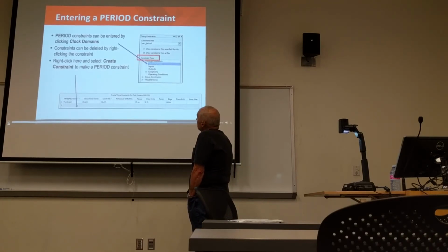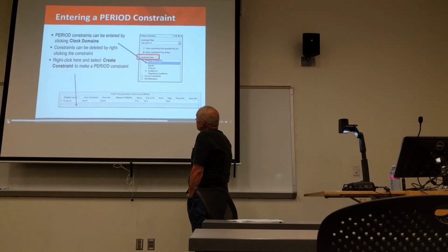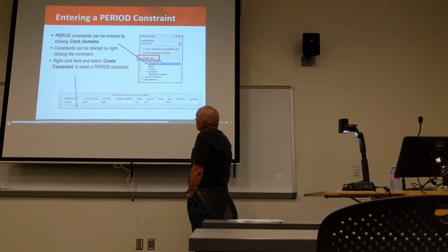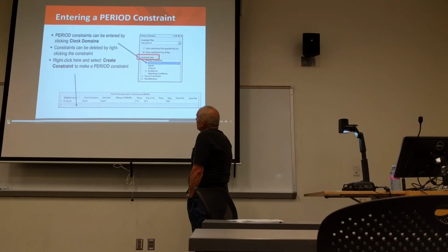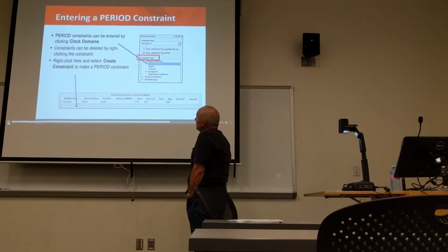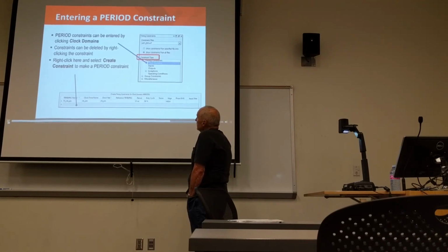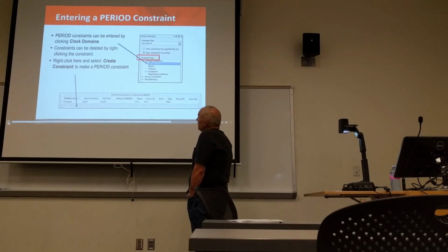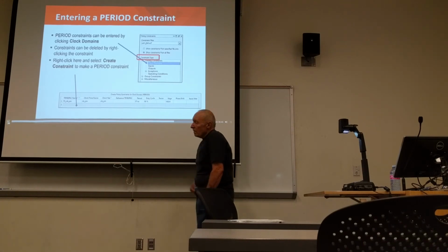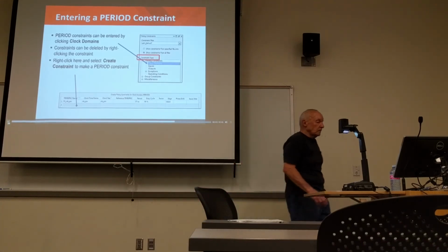The time spec name is automatically given as TS_clock_pin, and that's just a label. In fact, all they did was take that group name and put TS_ in front of it. The TS stands for timing specification. This makes it easier later on when you're reading your UCF contents to identify the timing constraints because they have the TS in front of them. So this is the label the timing constraints will be given in your UCF file.